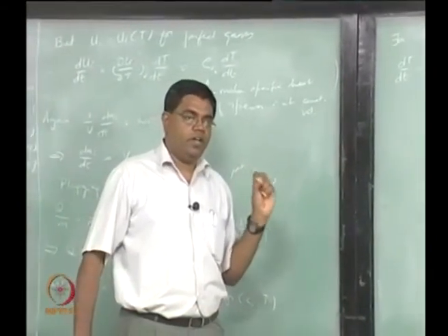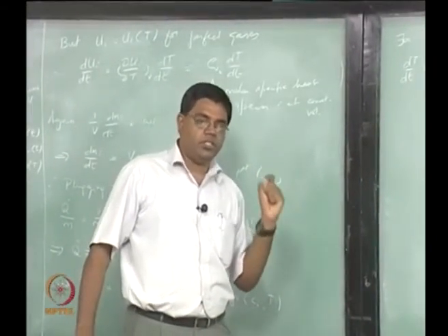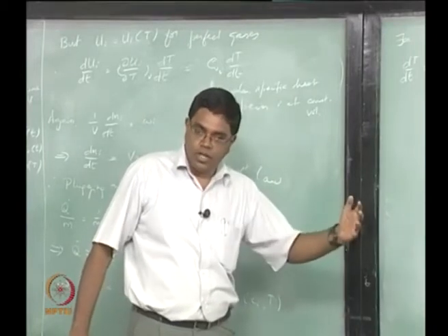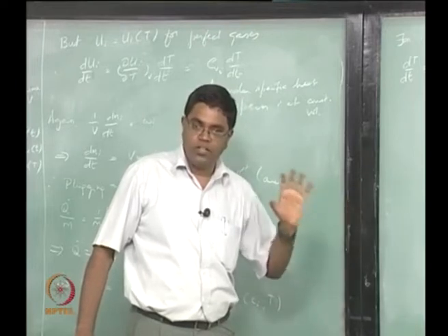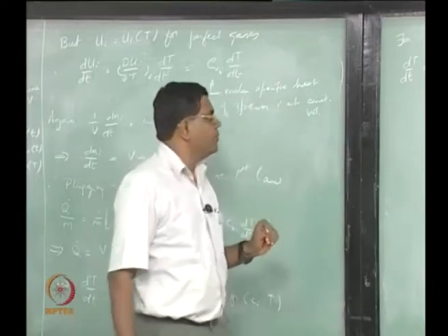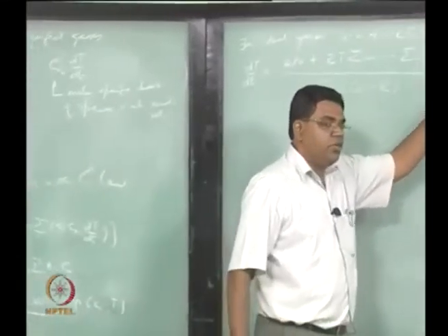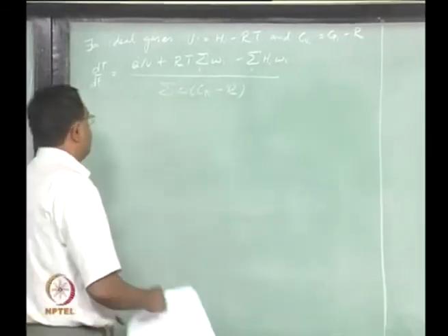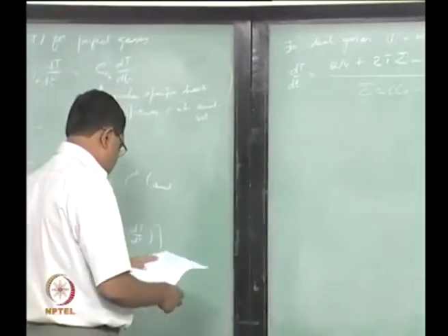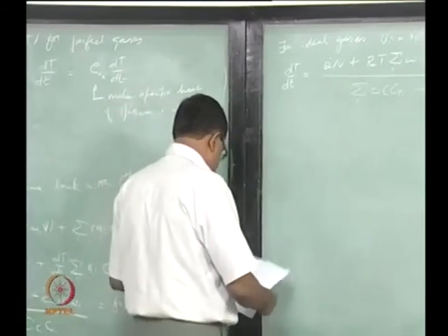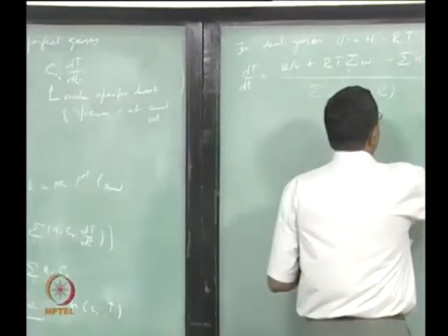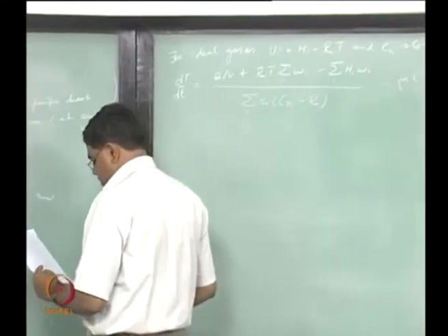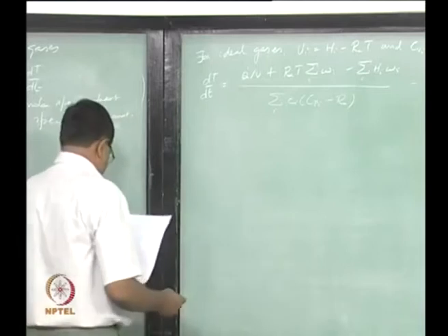So it is finally coming from the standard heat of formation times the rate at which it is formed, for every species added all together, is the total heat that is released in the chemical reaction. And then you will have a sensible enthalpy part that will stay. So these things will show up as we go along more explicitly. Don't worry about it now, just know this as before is a function of C_i comma T, keep that in mind.